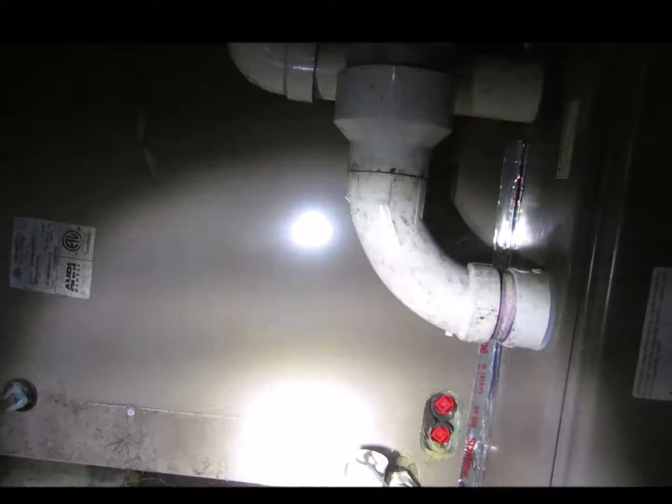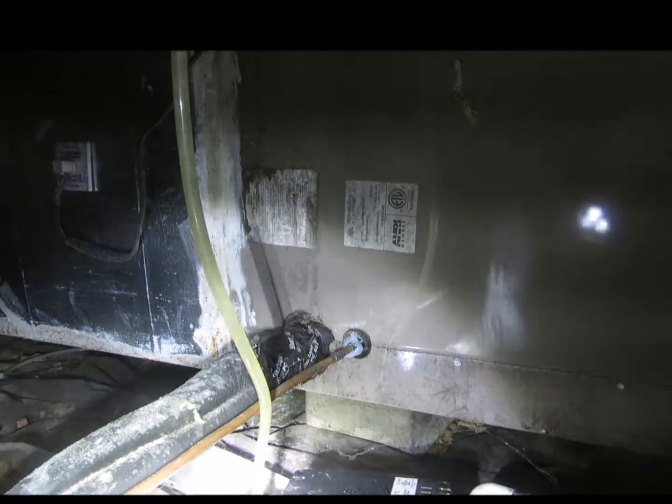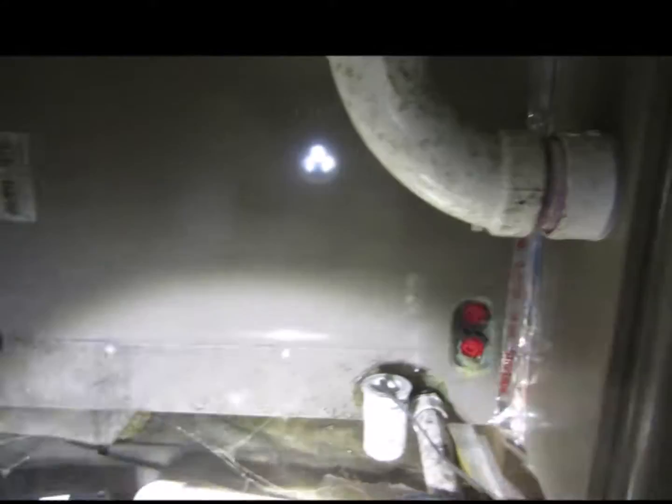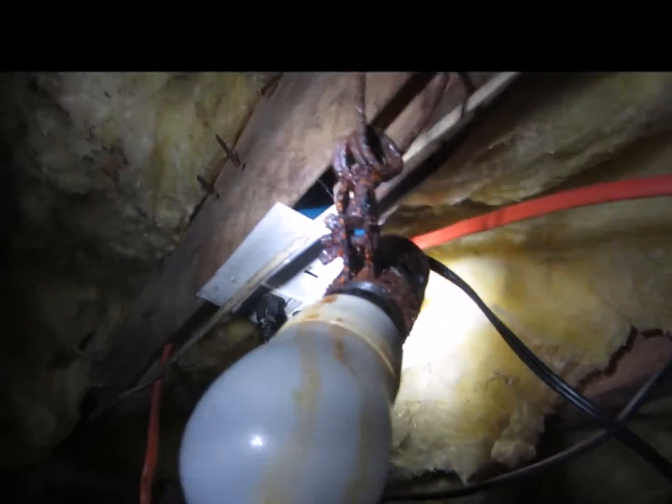There's no water in the overflow condensation line. The water in the pump is present and looks clear, so I'm assuming this pump is working. I don't see any drip marks, even though there's a bunch of mold underneath the air handler. Pretty much mold everywhere. Even extensive rusting on the light.